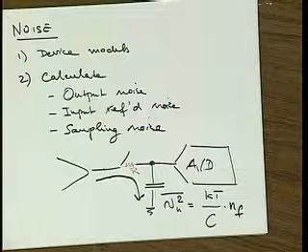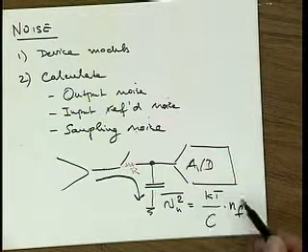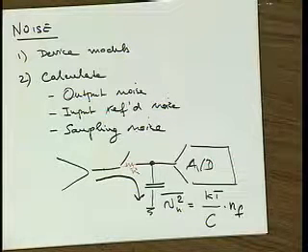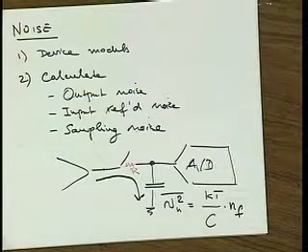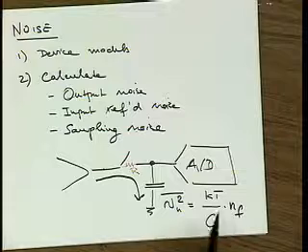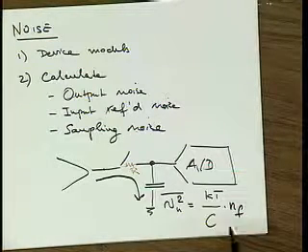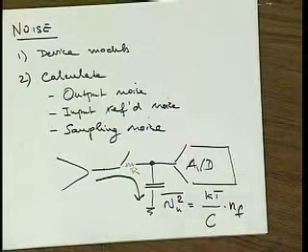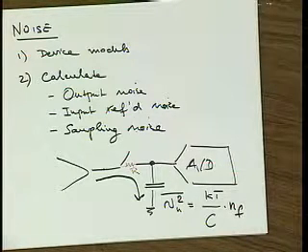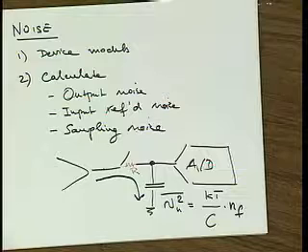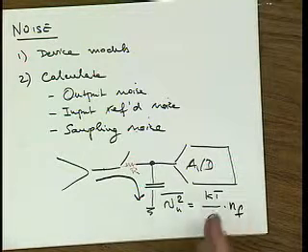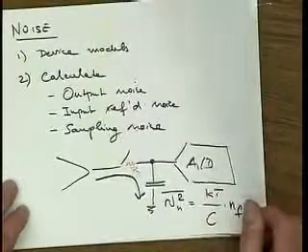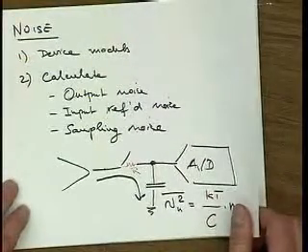But we'll talk about what is affecting the magnitude of how big this NF is. And the key thing is, again, the noise really has this form, kT/C. A very profound, very important result that we're going to use all over. The combination of kT/C with the noise factor tells us a lot about the noise in our circuit.